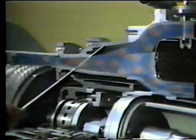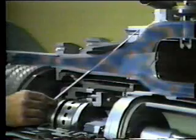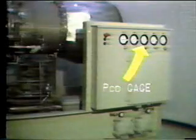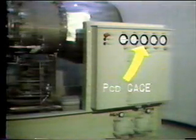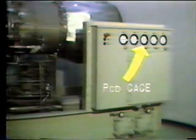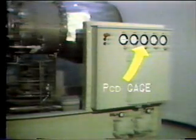Now, you learned in a previous lesson that air pressure is the greatest at the diffuser outlet and is labeled PCD. The PCD control indication system bleeds air from the diffuser outlet and uses this air pressure to perform 2 functions. First, it provides a PCD pressure signal to the gauge on the engine gauge panel. PCD pressure is a primary indicator of engine performance.